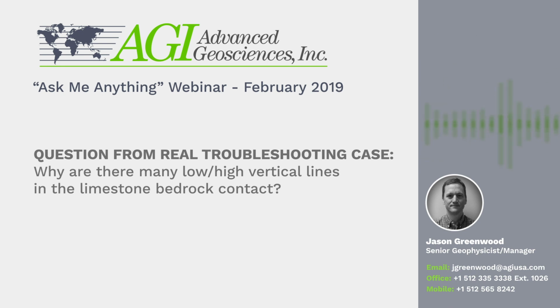That is a question that came up, and it had been nagging a customer working in karst areas. I was able to reproduce the artifacts here with the same data and then make them go away simply by changing the start model. And they had used a pseudo section start model, which is inappropriate for anything but a homogeneous case or a nearly